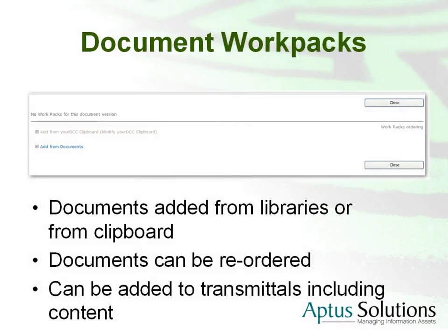Work packs are similar to document relations, where the documents can be added from the libraries or from the clipboard. But in work packs, the documents can be reordered, and they can be added to the transmittals included in the content. In other words, if a document is a work pack, then the contents of that work pack can automatically be added to a transmittal.